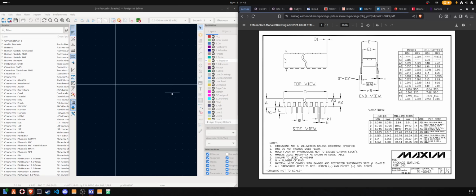This is a standard 2.54 millimeter pitch that you'd use on a breadboard, and so we can go in here and double check that. So for our pitch, it's lowercase e. So if we walk over here to our lowercase e and go to millimeters, 2.54,